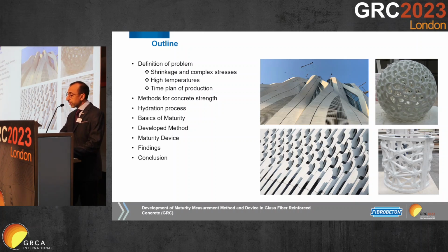Maturity refers to the cumulative effect of time and temperature, so that we can make informed decisions regarding the demolding, handling of the GRC elements, and also selection of the mold types as well. In the pursuit of advancing the maturity, a developed method has been introduced, and we will be sharing with you that method.